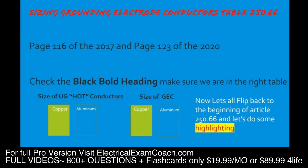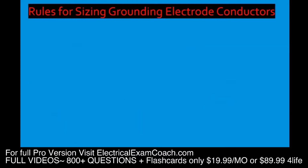You're either going to size it based off of table 250.66 if the electrode is not mentioned, or if the electrode is mentioned in your question or in your real world scenario, you're likely going to be using Article 250.66, parts A, B, or C. And we're going to go through this step by step. Let's get to it.